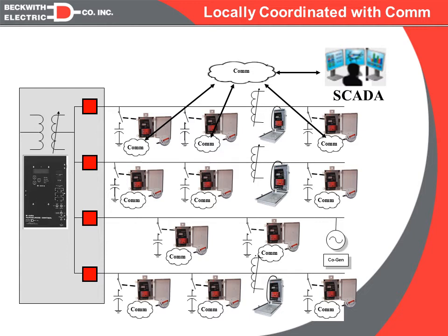With that in mind, here's what the architecture would look like for this system. So all we've done is we've added a SCADA, we've added two-way communication. Typically we don't even interface with the regulator controls, because our main concern is just getting neutral current back for the health of our capacitor controls. We could add communications to the regulator controls and get some information back from them on their health also, but in most cases it's mainly the capacitor controls we are interested in. And again, we have no control functionality here. This is metering and status only.